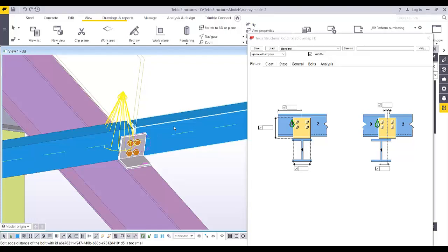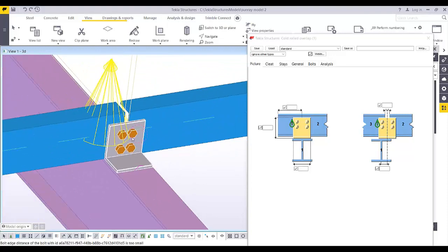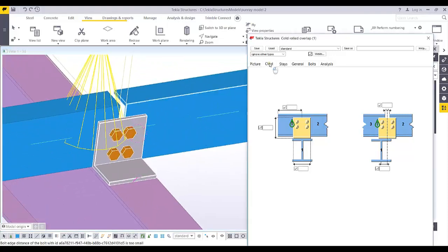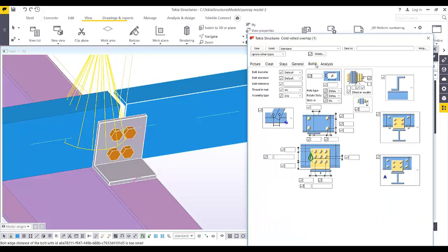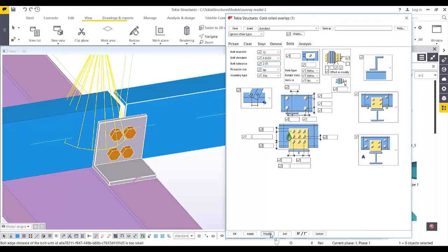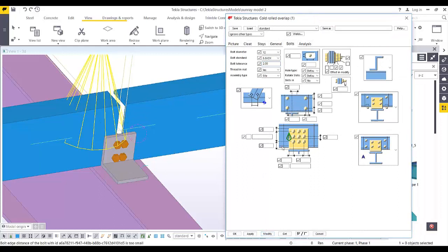But if it is something like this, if the purlin is a bit thicker, or maybe 5 mm, so you bolt it like this. So in this case, for the cleats, maybe we just use 12, and then this, and then 2. Okay, modify. All right, so here, let's say, if this one is 80, maybe 100.